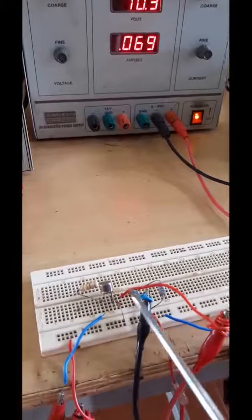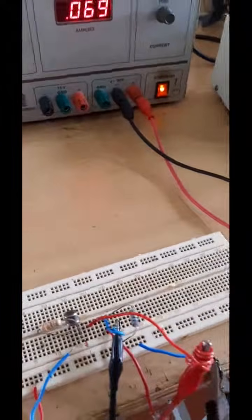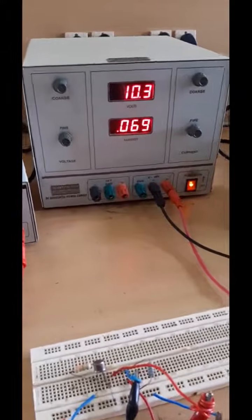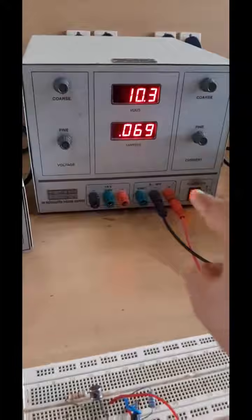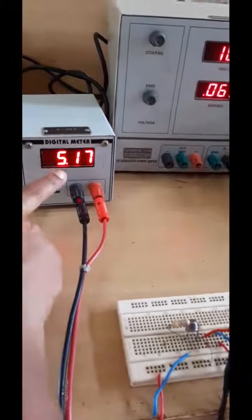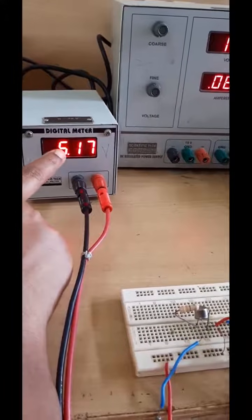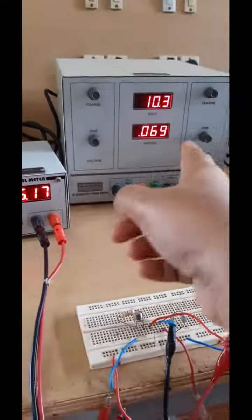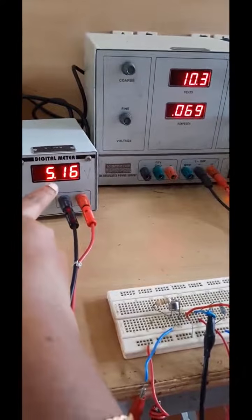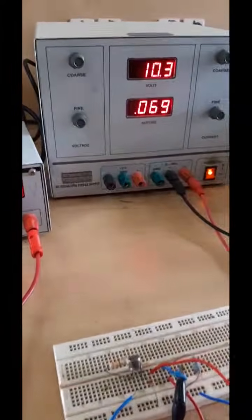Okay, so this is the circuit setup, and next we set the input voltage to 10 volt. So what will be the output voltage, and that will be displayed on this voltmeter. You can see here that this is 5.17, that is near to 5 volt. That means whenever the input voltage is 10 volt, the output is regulated to a voltage of 5 volt.